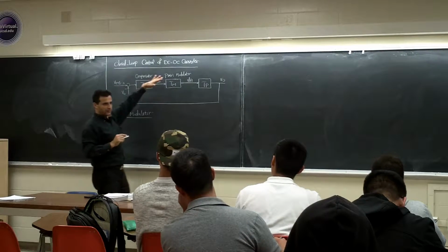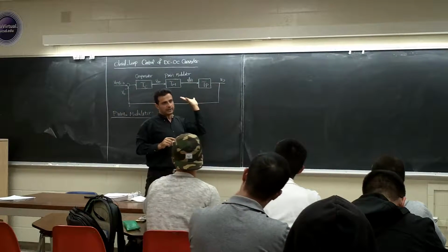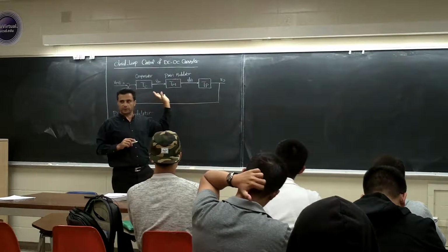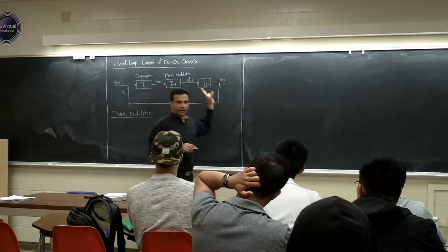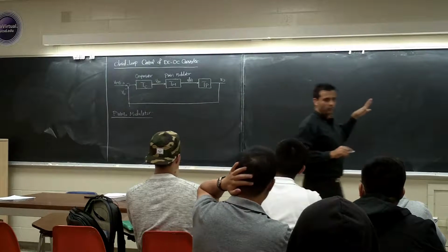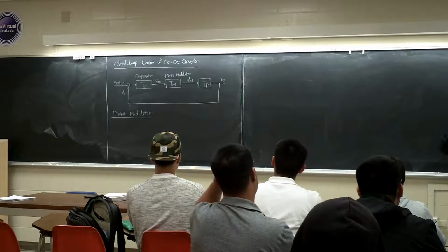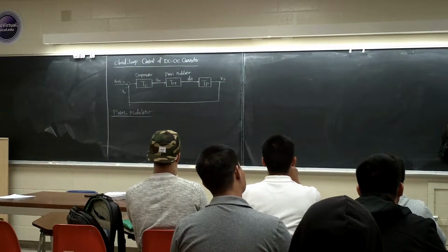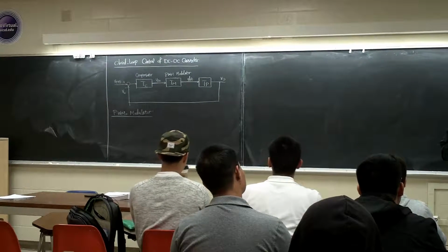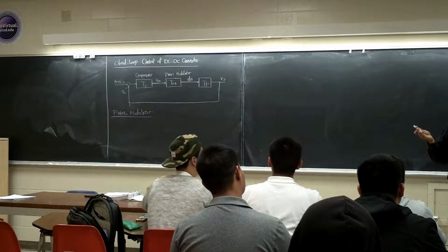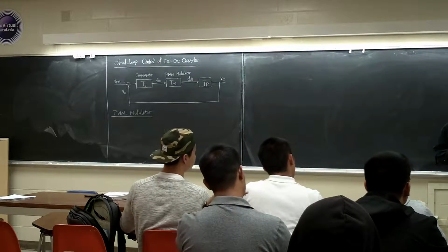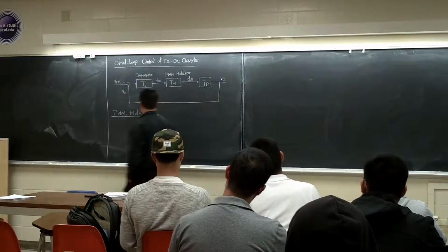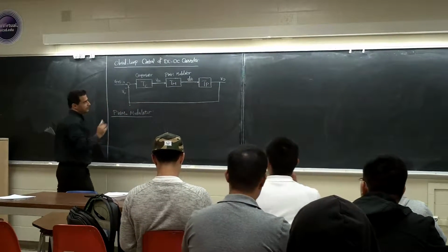There's a control signal coming here. We need to translate that one. We need to change that control signal to the on and off signals, right? Like what we did for the three-phase inverter. We had an MA, MB, MC coming in. We compared it with a triangular waveform, right? And we say if it's more than that, it's on. If it's less than that, it's off, right? And we went through the equation for that. Here we select a simpler sawtooth.